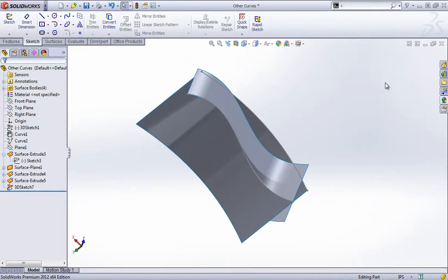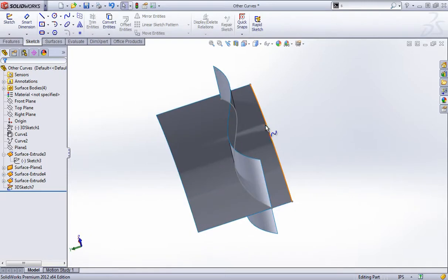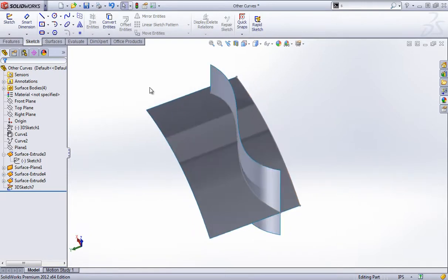You can also use the intersection curves in a 2D sketch, but depending on what you're using, in this case we're using two planar sketches, it'll simply select over whichever edge is parallel to that plane. But if you have a more complex intersection between two non-planar surfaces, then you can convert over that edge to a 2D sketch plane and you'll have a slightly different curve to work with.